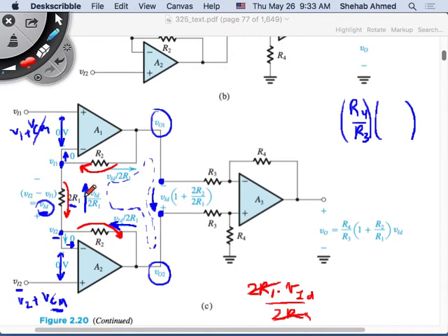Okay, so now let's apply that. This is going to be the voltage that I have here. Those two voltages are equal to each other. There are two nodes, and I want the voltage across that. I want the voltage that's going to my difference amplifier. Because I made the difference amplifier high input impedance, no current will flow. That's the trick here.